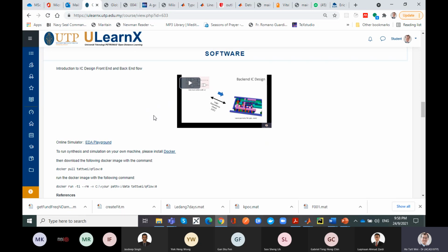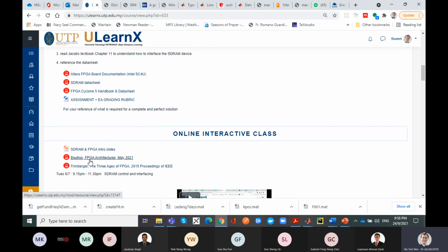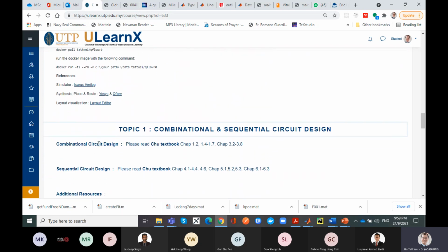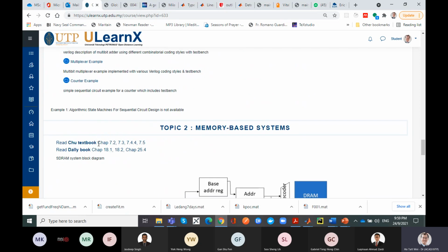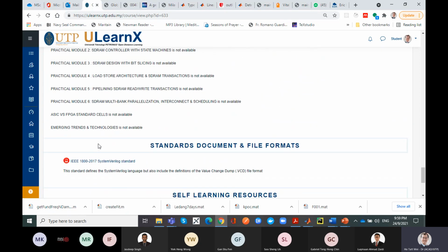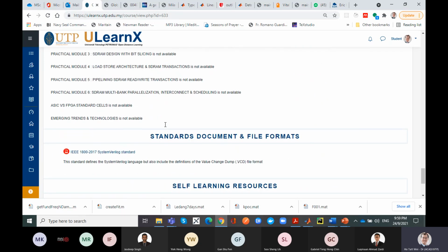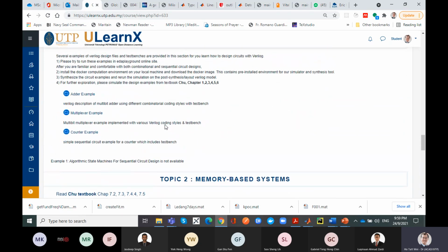FPGA, you don't. If you go through my introduction video plus read this very recent paper on FPGAs, you find that FPGAs actually don't have logic gates. They have lookup tables, which is actually a form of memory, and you implement logic gates that way. So it's a bunch of memories interconnected by crossbar switches, and what you do is program by implementing a lookup table in the memory, and then selecting the connectivity of the crossbar switches. Okay, more on that later. If you don't quite understand what I said, you can write it down and ask me later, but I also hope to cover it.